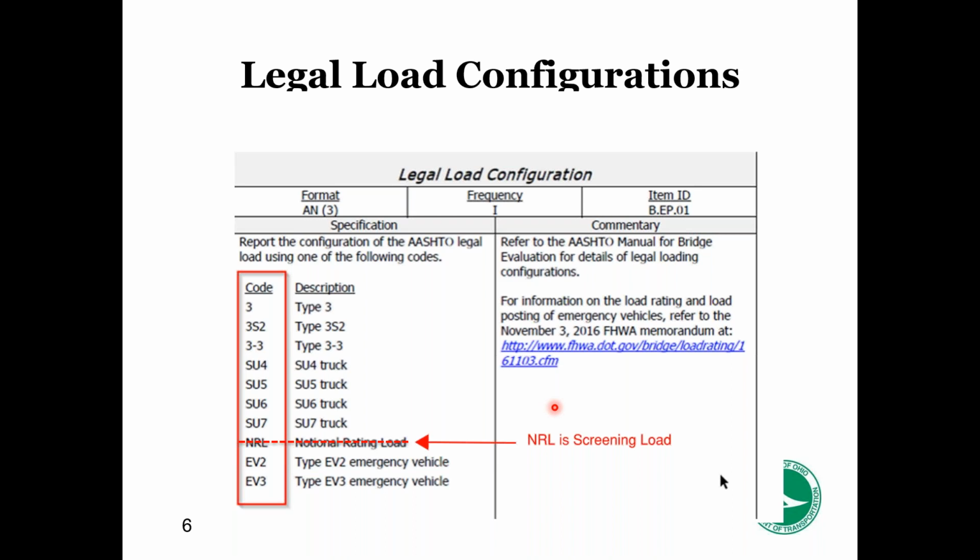So remaining from this, these are the list of loads required by SNBI. There are 3 new loads we determined from this list. These need to be included in our rating process. There are 3 Ohio trucks which we use. For example, in this list, the type 3 load is a 3-axle vehicle. There is no 2-axle vehicle. So as a part of ODOT policy, we have a 2-axle vehicle, the 2F1, and also a 3-axle truck and a 5-axle semi in our group of rating vehicles.